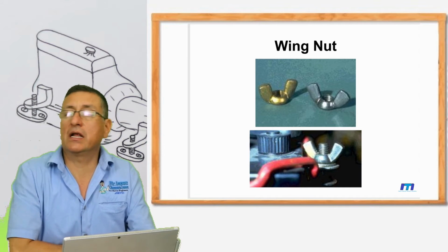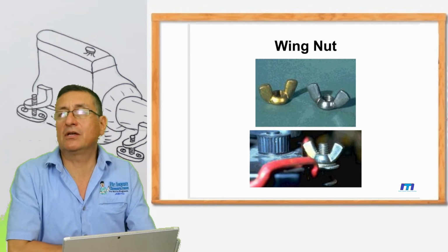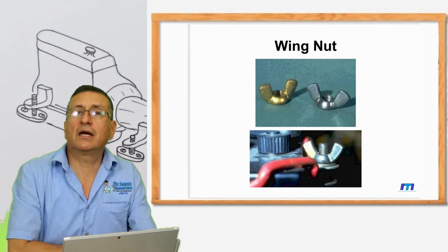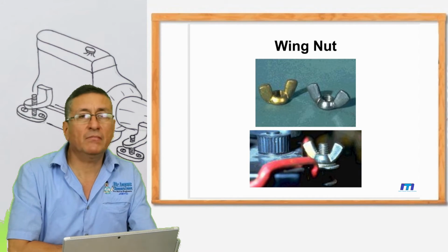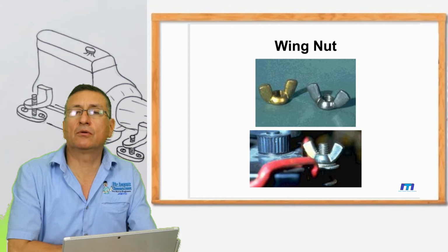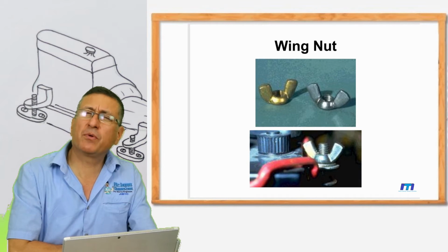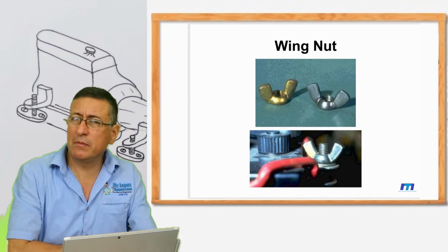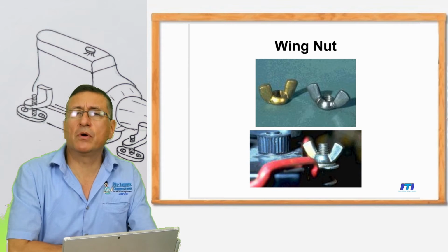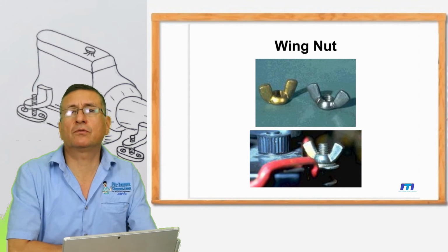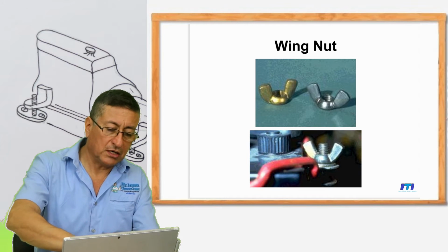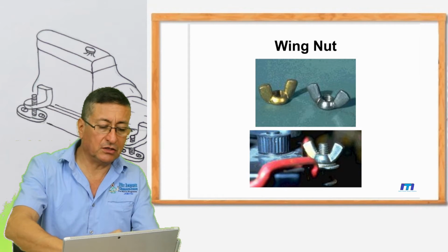The wing nuts are not authorized in marine application. Most people install the battery cable on the battery terminals with wing nuts. The wing nuts are not authorized. I think so, probably in small boats, but in medium and big boats, no. For that reason, keep in mind that wing nuts are not authorized. No wing nuts. Under any condition install wing nuts.